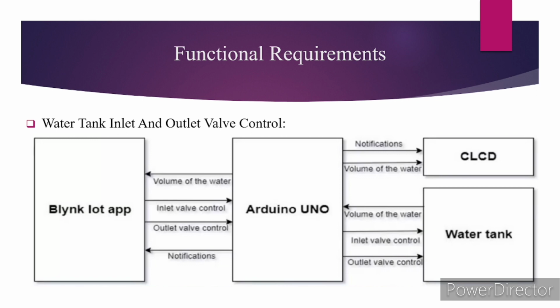Lastly, we have to control the volume of water in the water tank by turning on and off the inlet and outlet valves of the water tank, reading the values of water level through serial communication, and displaying it on the CLCD.